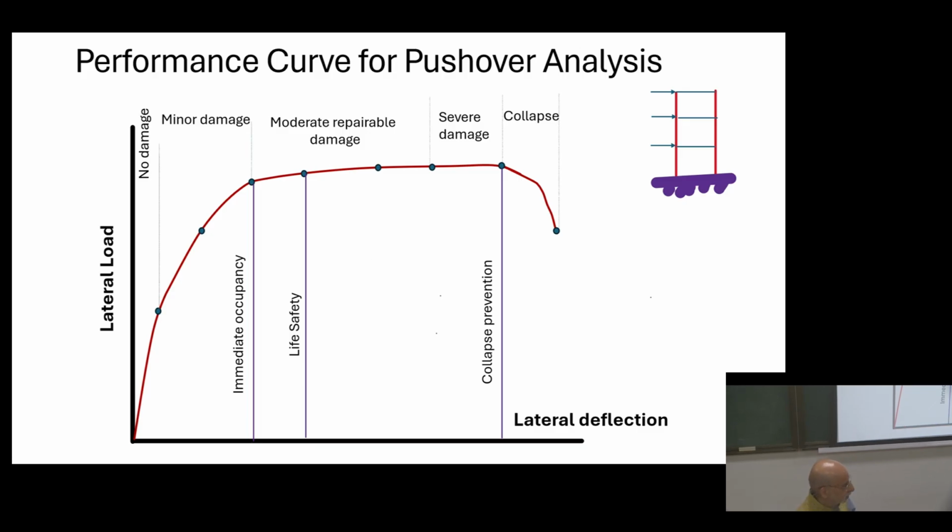So you push it slowly. You are not applying the force precisely. It's an equivalent system; you calculate the deformation and the stiffness. That is what I told you, stiffness becomes important in addition to strength. However good the strength you use, if stiffness is not sufficient, the structure is not going to sustain it. So both are equally important.